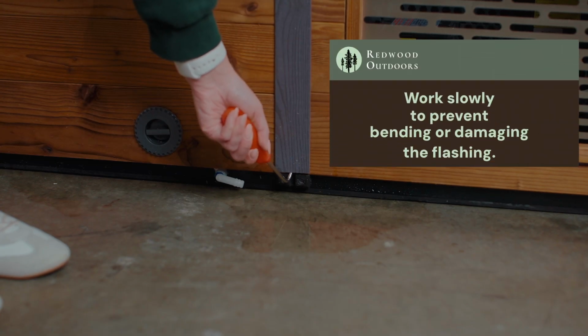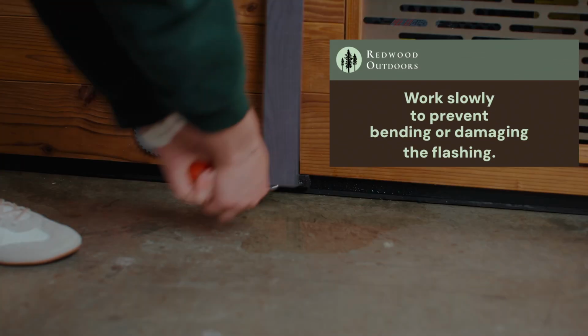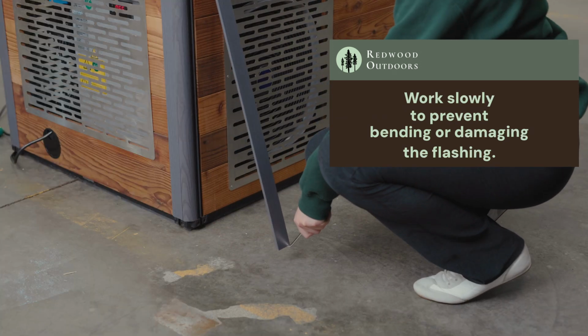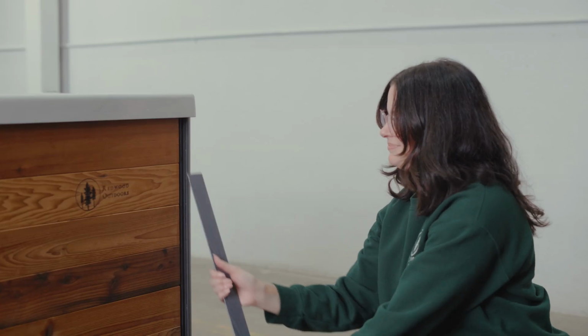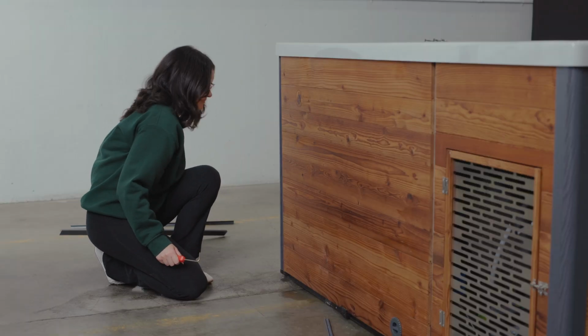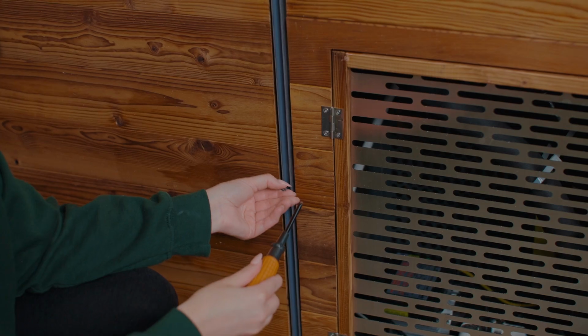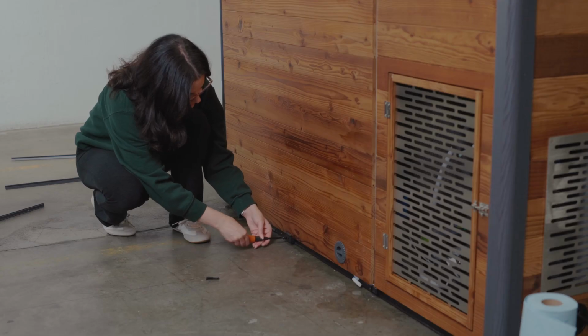Start by using the hook tool that came with your plunge to carefully but firmly lift and remove the metal flashing sections surrounding the wooden side panels. Corner pieces of the flashing are fastened with screws. These screws will need to be removed before the rest of the flashing can come off.